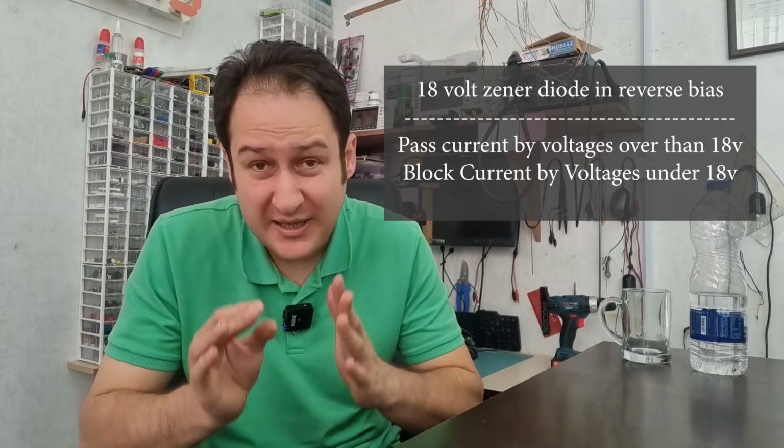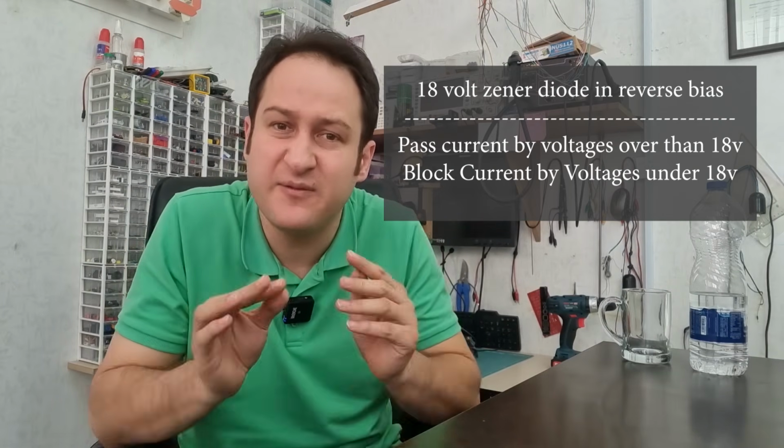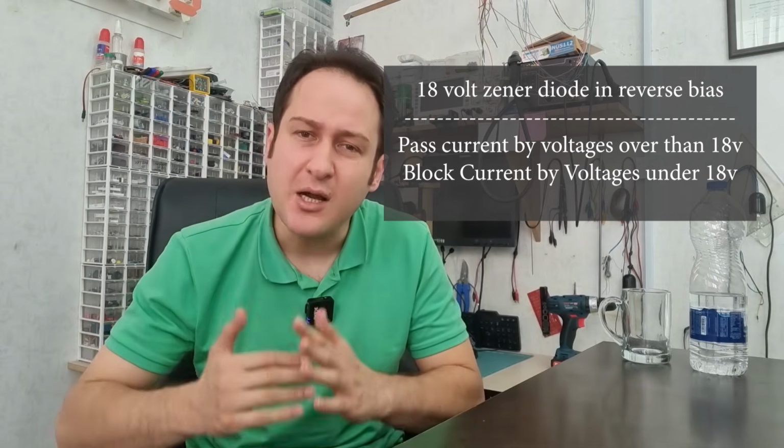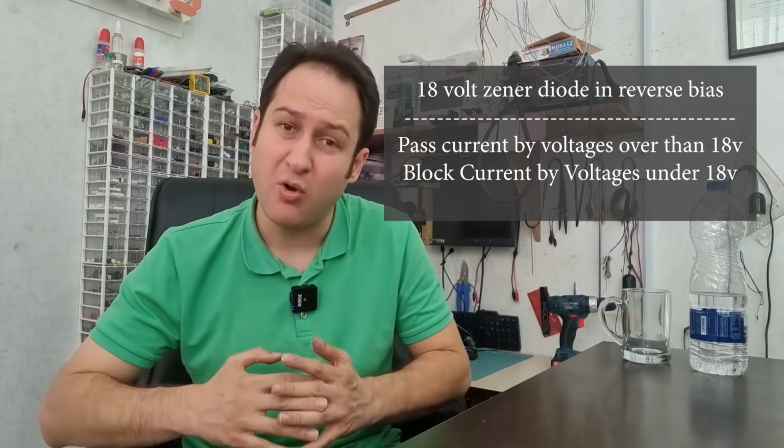Let's consider an 18 volt Zener diode. It means in a reverse bias setup, it will block current at voltages under 18 volts and start to pass current at voltages over 18 volts, and it will do its best to keep the voltage across itself at 18 volts. Notice that we are talking about an ideal Zener diode.